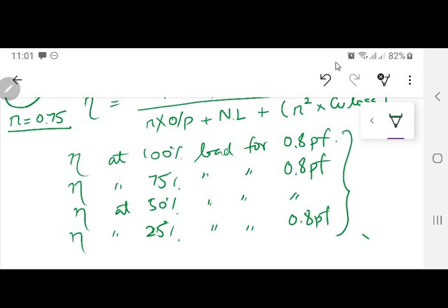And 0.8 is not a very good power factor overall. If you are in a residential area, 0.8 power factor will be almost there. But if you are in some industrial area, supposing you have commercial motors or induction motors there, the induction motors, if they are running at no load, will exhibit a power factor even less than 0.3.